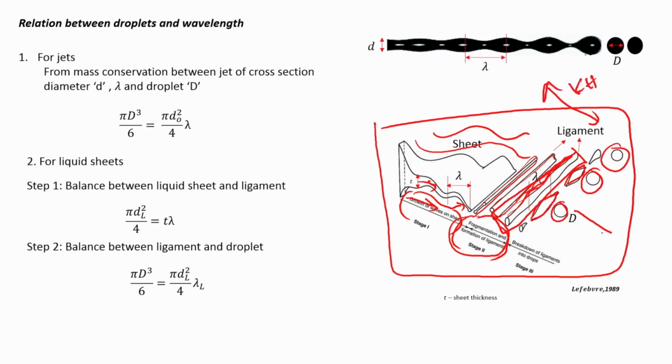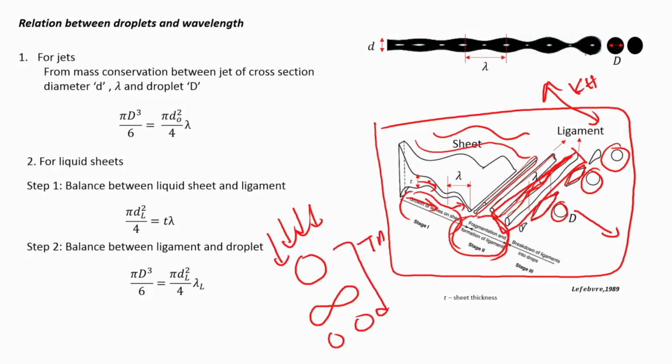Even when this droplet forms, these are nice and round droplets sometimes, they still face this aerodynamic load around them. So, these droplets can undergo that kind of breakup, which is basically like the TAB. So, the TAB model is good in the case of secondary breakup. These droplets however can also undergo oscillations like this, and then it can split. That will be more like KH or Rayleigh-Taylor or something like that, got it. So, there are two pathways basically.